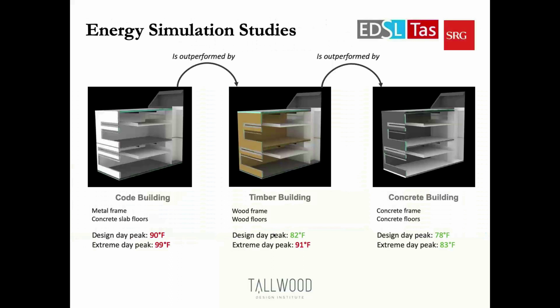We have a really excellent Energy Studies in Buildings Lab at University of Oregon that has been doing really exemplary building science work for 30 or 40 years. And some of the projects I just wanted to quickly touch on that they're doing. One is looking at how mass timber buildings can perform equally to concrete buildings in terms of thermal mass, where the concrete helps to even out the temperature flows in the building, basically absorbing heat during the day and releasing it gently at night.